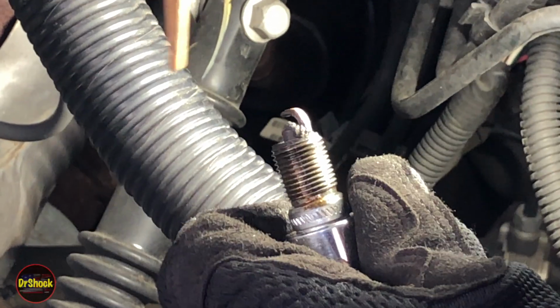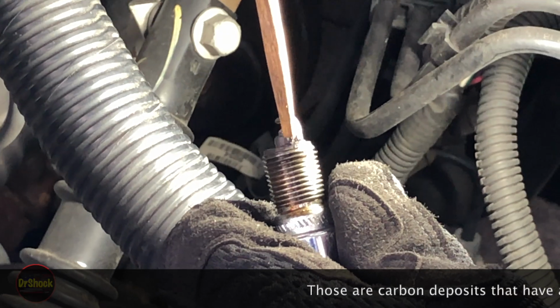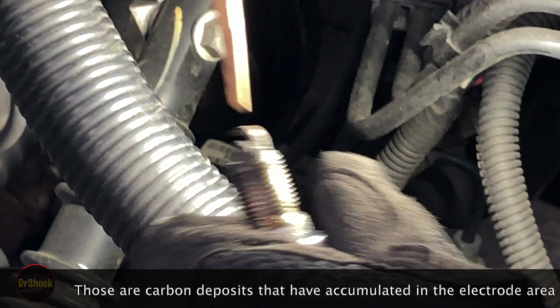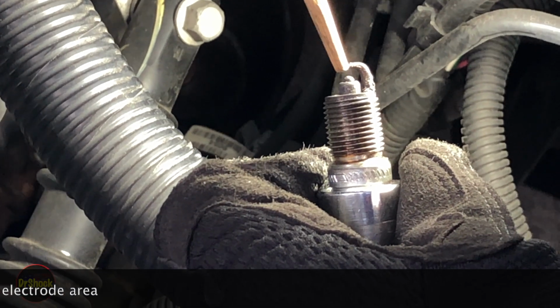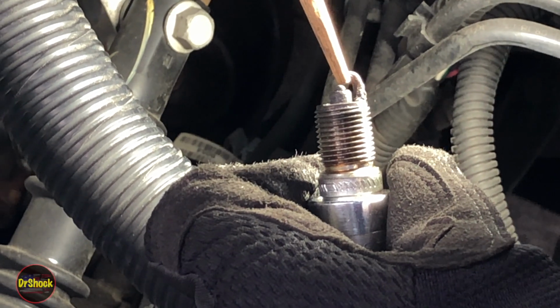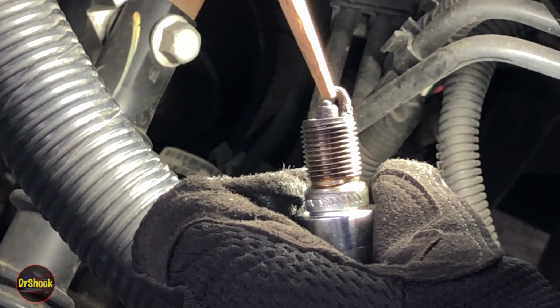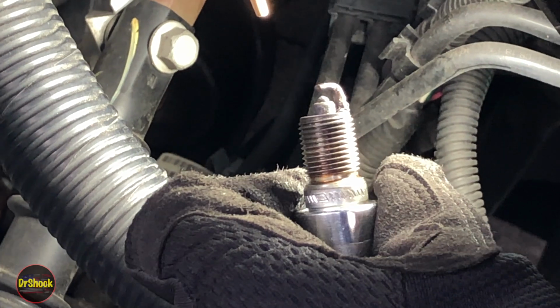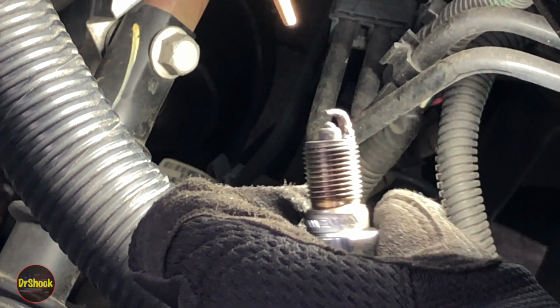But if we zoom in here, what I don't like is this deposit that we see right next to that part of the conductor. But what I mostly don't like is if you take a look at the gap, this iridium electrode is burned down. You should be able to see a very thin center on that iridium electrode. And that gap should only be about 40 thousandths on a factory plug. You can just tell looking at this, that's not 40 thousandths. Let me see if I have one of these plugs on the shelf here. I might have, I don't know if I do.